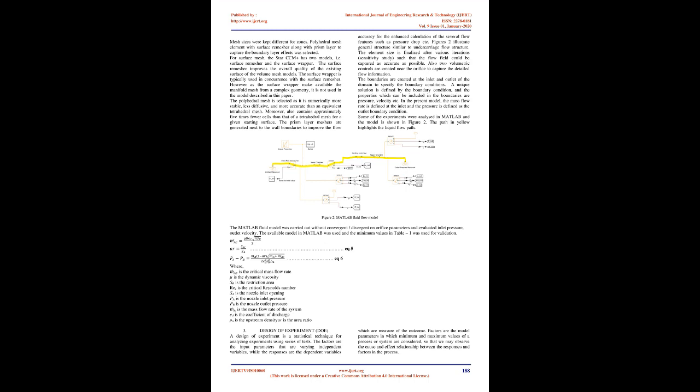Evaluation using factorial design to identify significant factors, and an estimation of the response function. The parameters inlet angle, outlet angle, orifice thickness (in), orifice base thickness (in), orifice diameter (in), Q mass flow rate (lb/s), and outlet pressure (psi) were studied for individual influences on the responses. The possible interactions between the input parameters and each response will provide additional interaction terms.